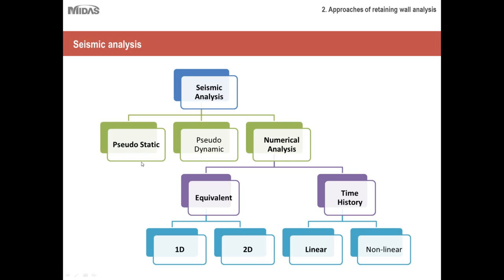But for now, you can just understand that pseudostatic is a set of formulations which considers the mass of the structure to be at rest and not in a dynamic state. It just considers the mass of the structure at rest, which would cause a certain amount of horizontal or vertical force onto the structure when excited under an earthquake.